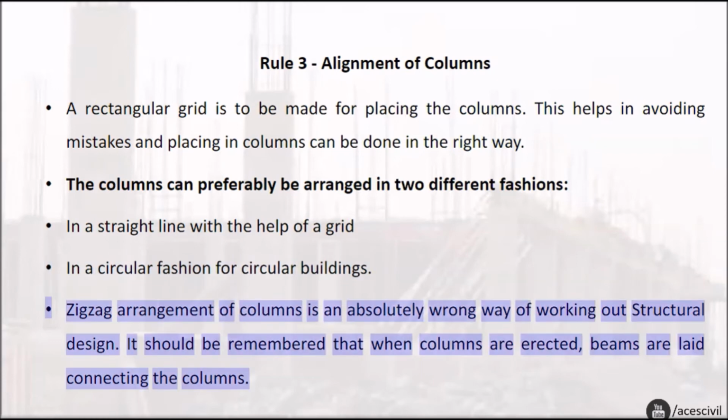Zigzag arrangement of columns is an absolutely wrong way of working out structural design. It should be remembered that when columns are erected, beams are laid connecting the columns.